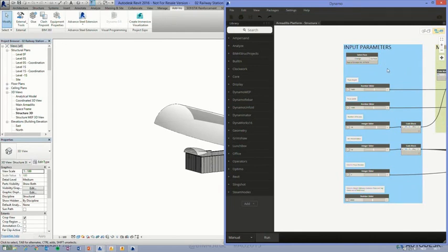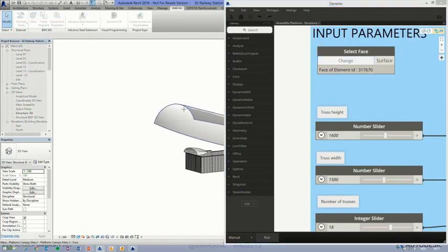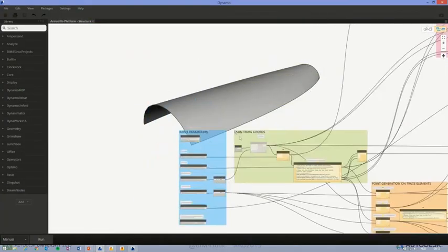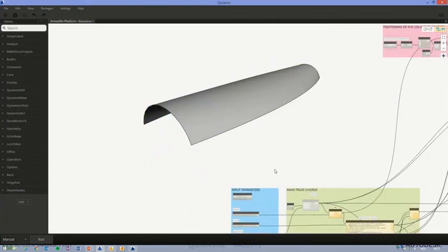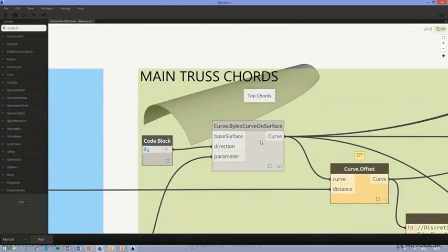Now, the platforms that I'm going to use: you have to know in Dynamo there are two versions of Dynamo. We have the open source version, which is integrated in Revit. So if you have a Revit license, then you also have that Dynamo license, which is called Dynamo 0.9. But we also have a product called Dynamo Studio, which is exactly the same. So if some of you don't have anything of Building Design Suite or Revit and just have a license of Robot, then you don't have that Dynamo plugin working. So therefore you can use Dynamo Studio, for instance. I'm going to show you both of the packages, and you won't notice any difference, because there isn't a difference. It's exactly the same product.